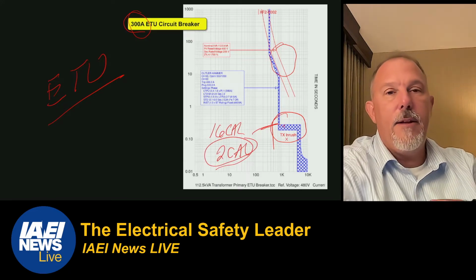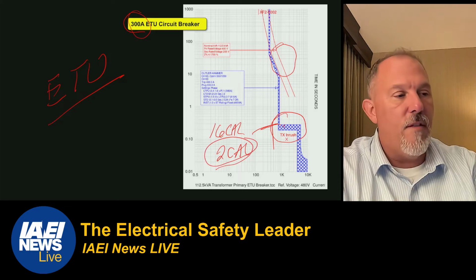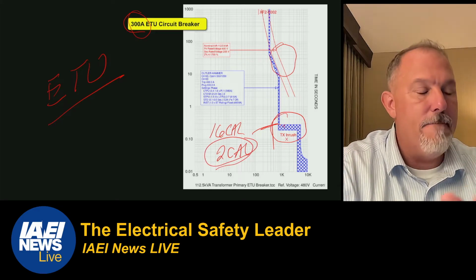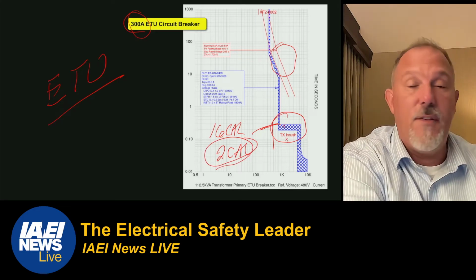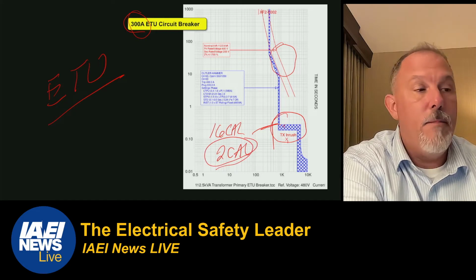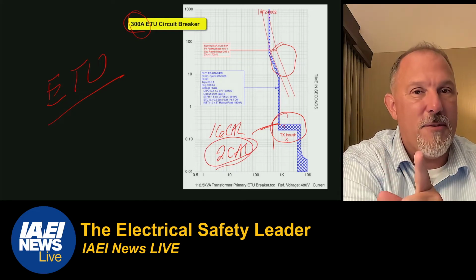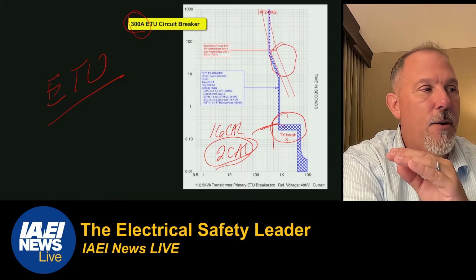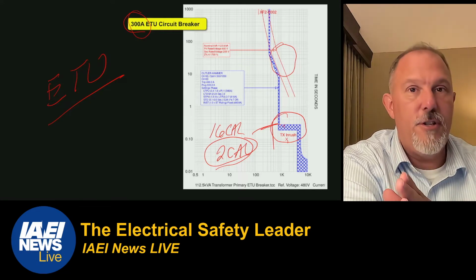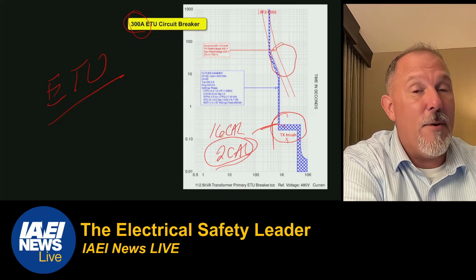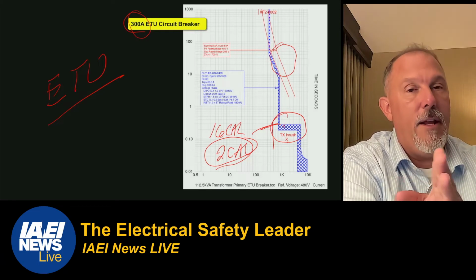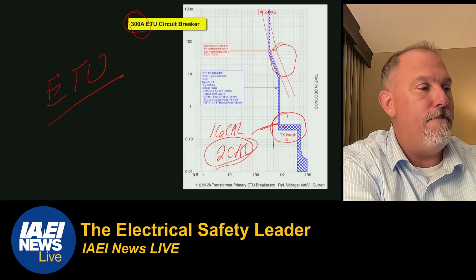Okay, I can get my incident energy lower from a short time delay that lets the inrush currents flow, but only those inrush currents. Any current that is in that inrush range and it persists longer than what it should, then that device is going to take that out.